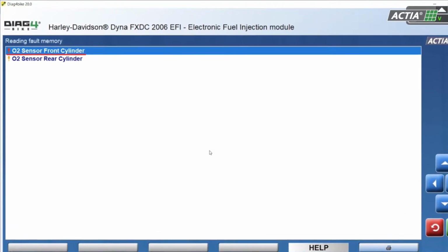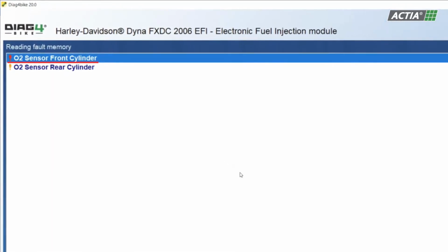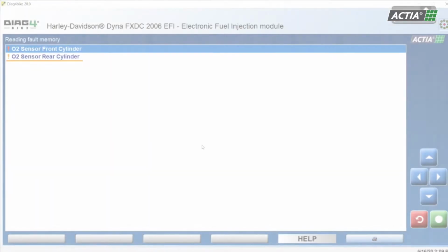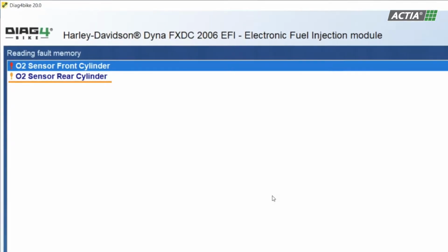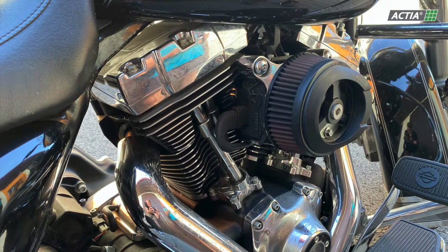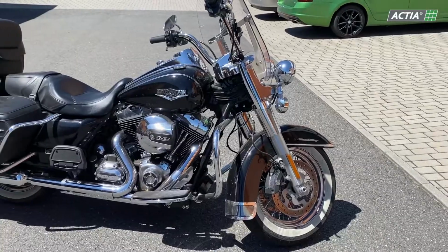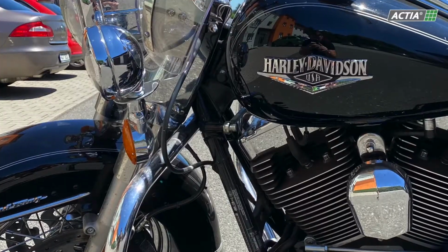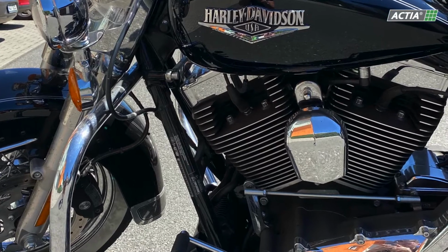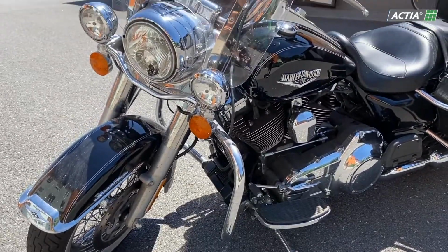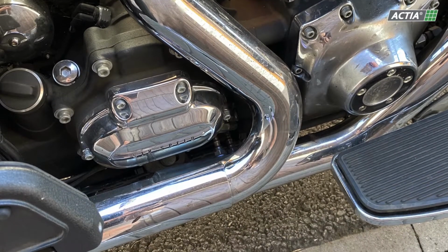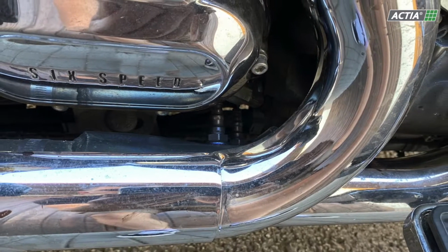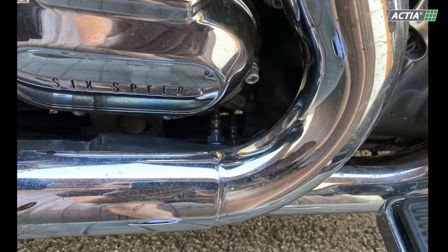It is important to know the error codes are differentiated into current, which are highlighted in red in the program, and temporary, which are highlighted in orange. The latter have occurred in the recent past. In some control units, temporary error codes may delete after traveling a defined number of kilometers. It is also important to realize that some faults may be indicated only after, for example, letting the engine warm up and traveling a certain distance. A typical example of this is a fault in the oxygen sensor.